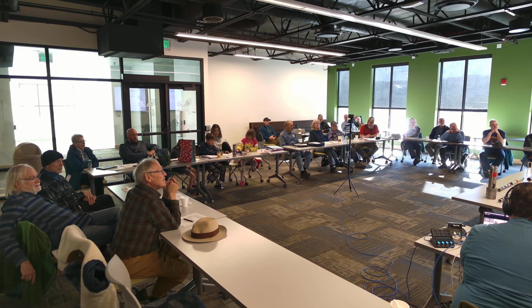So we would use mud pulse in areas such as a salt zone where the EM tool won't work. Then we have to rely on mud pulse. Mud pulse is actually the first technology that they used before this came out. But it's still utilized today because you can only drill so far, and our batteries will only push out so much power before there's no more signal left. So how long ago did you start using mud pulse? Mud pulse is probably back in the 80s, I want to say.